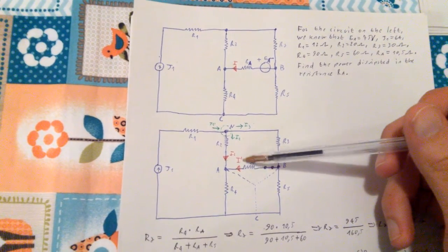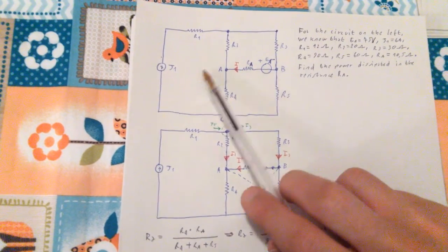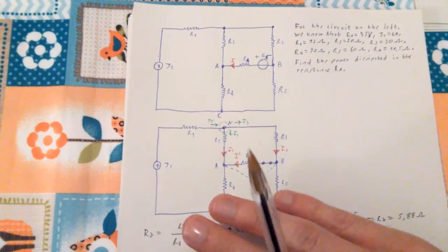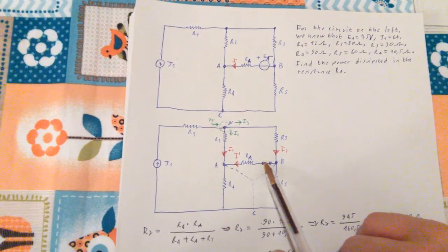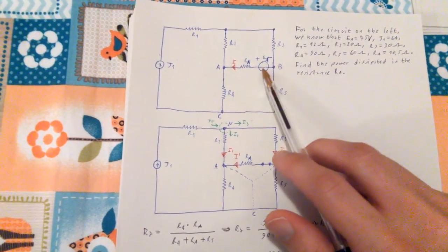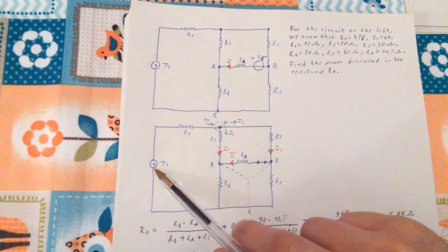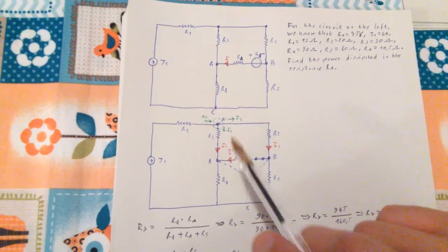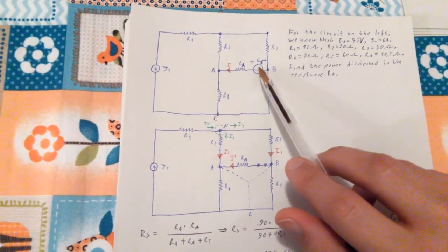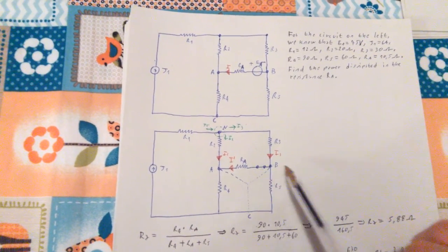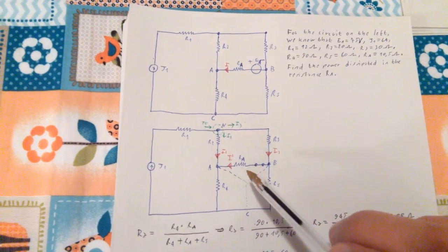The reason is that we had two generators, a generator of voltage and a generator of current. We made a short circuit instead of the generator of voltage, and we just considered the generator of current. So now I'm going to do the opposite and consider the generator of voltage. Therefore I'm going to find something called I second.